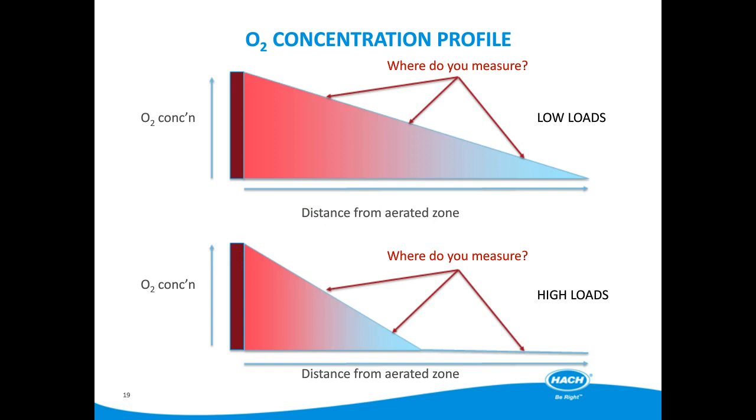So therefore there is no location for a DO probe within the ditch that provides a representative value of the dissolved oxygen concentration. So although DO concentration is important, HACH would recommend that consent parameters, that is ammonium or nitrate, are measured to comply with consent.